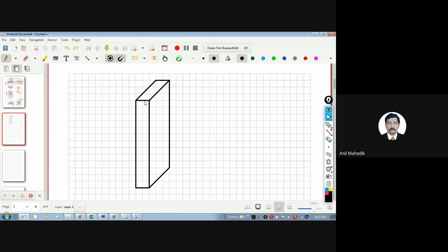So we have an axial load here on the column PU, and let me assume this as x-axis, xx, and this as y. Okay. So all of you know that there is a moment like this. So there is maybe mx, and there is a my, about x, about y. So this is nothing but biaxial moment.